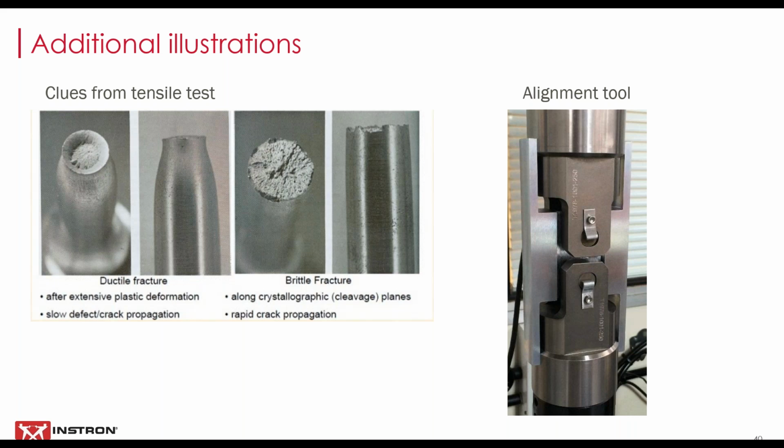So if you're seeing that really ductile behavior in tensile, then I would immediately start looking at a J1C type test. But if you've got something brittle, then certainly attempt a K1C test. It is far simpler in both analysis and in test preparation. I hope that helps and that's fairly clear.